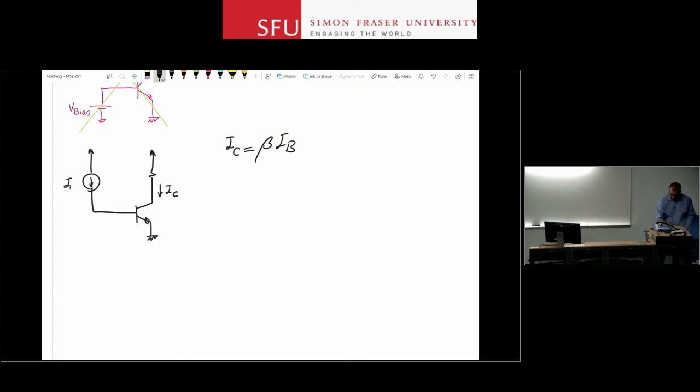This is going to be my I bias, and I know that in this case, IC is beta I bias. Done. I established the current that I wanted very, very easily. Stop for a second and just think about this and tell me why this is also a bad way of biasing. You're not going to get what you want.